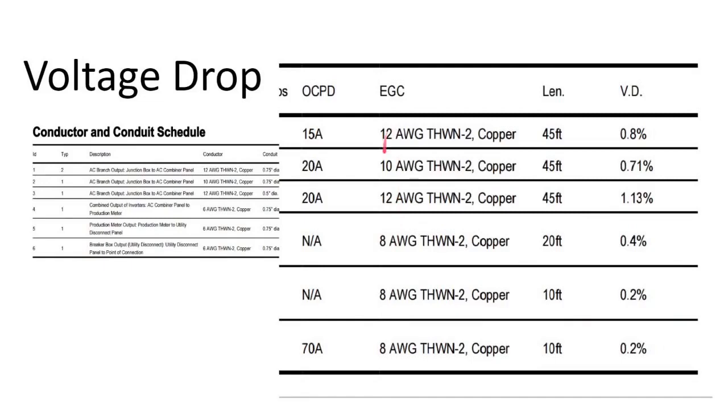You might be looking at this material list and saying, well, why don't we simplify it? And sometimes you can oversimplify, like using number 8 cable for every circuit just to only have number 8 cable. That could result in you spending too much money on your cable budget. But if there is just one oddball, saying, okay, well, there's two circuits of 12 and one circuit of 10, but look, this circuit of 12 actually has some voltage drop to it.